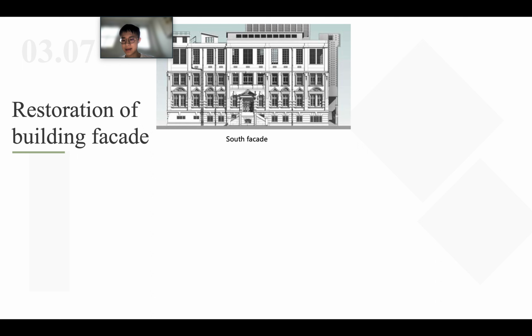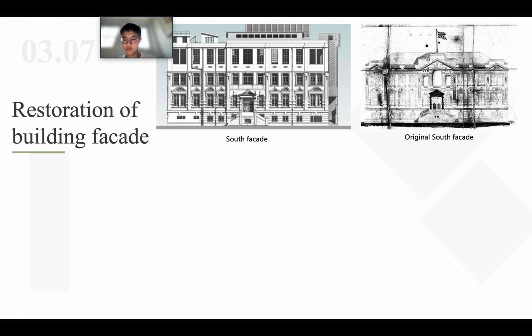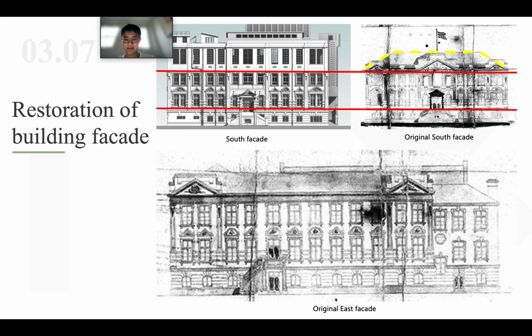After that, because the original four-hipped roof was demolished in the process of historical adaptation, and now we want to restore it, we can only determine the two ridge forms of the building based on the perspective restoration of historical photos and the angle of historical drawings. Everything is kind of blurry, but after all, it turns out to be good.